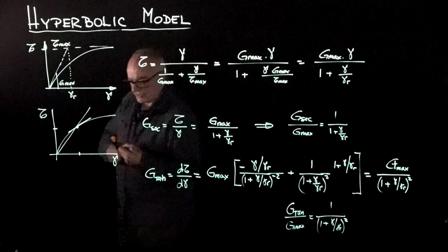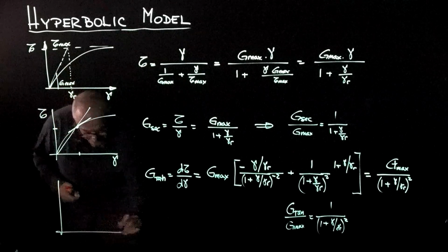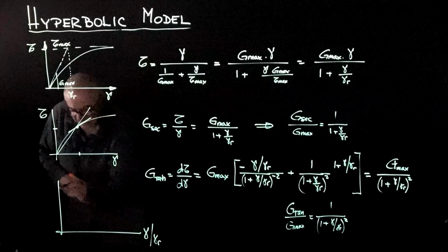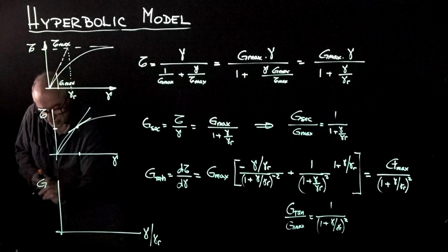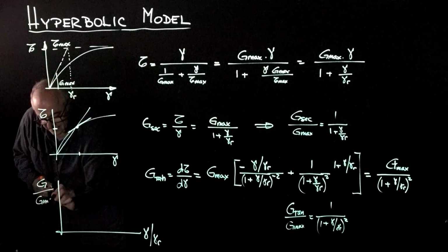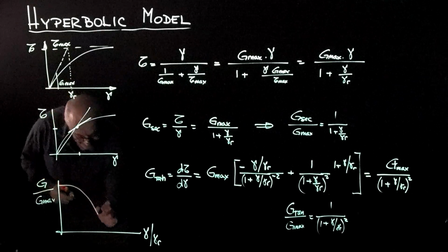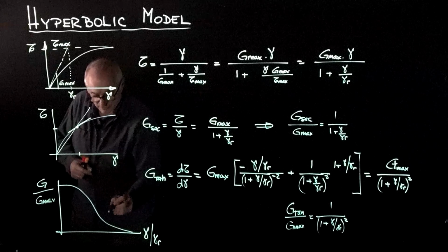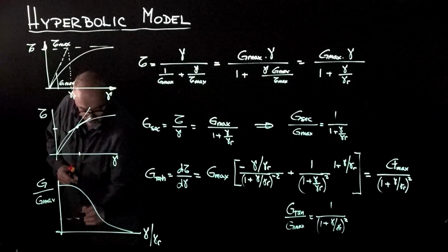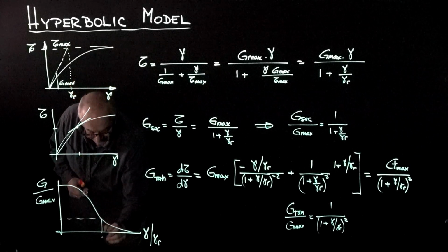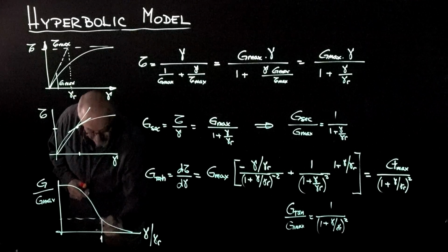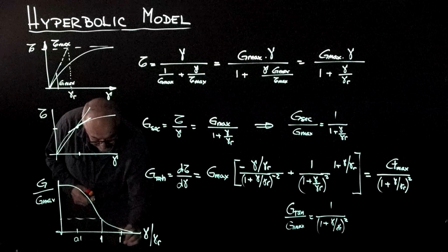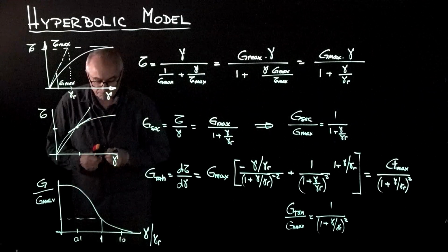You can plot both of them, but in general, they look as follows: gamma reference, and this is G tangent or secant over Gmax, and the curves are like that, as you have come to see. Depending on whether this was G tangent, then this would have intersected at 0.25. This is when gamma over gamma reference is 1, and this will be 0.1, this is 10, etc.